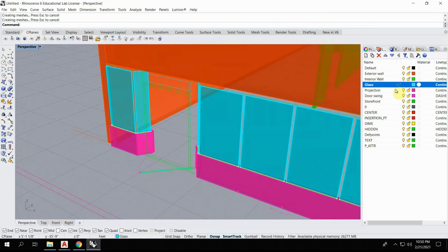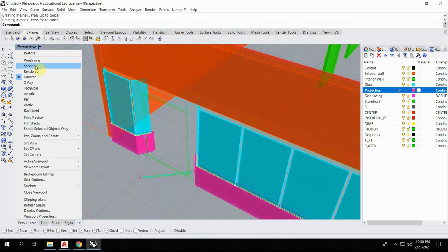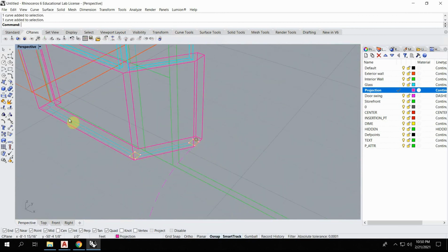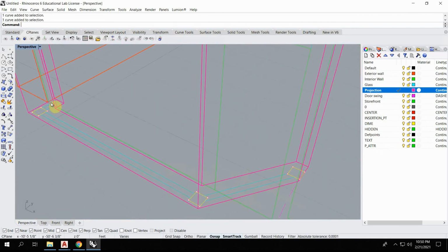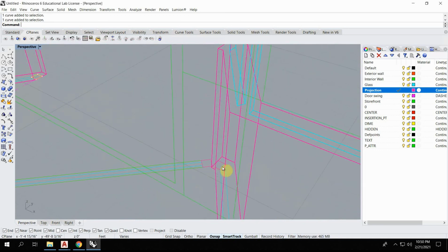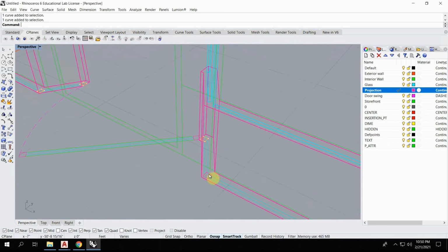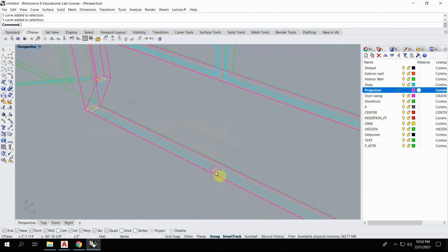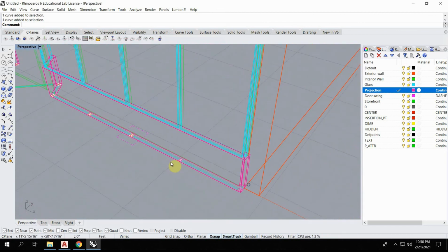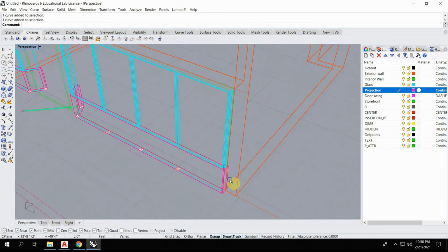So the first way you can try mullions is very similar to what we just did. So you would go back to wireframe just so you can see this. Select those mullions that we made. So those are all those rectangles. And notice I'm not doing the door because I know the door has different dimensions. It would be the same process, just you would extrude at different amounts for the door.